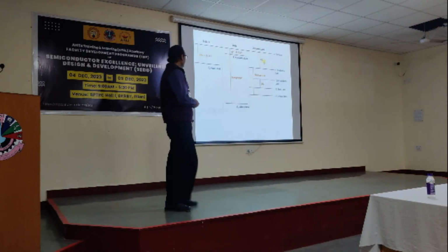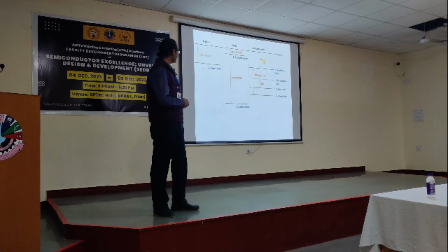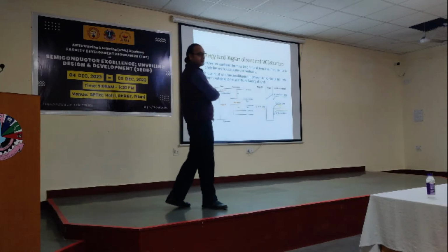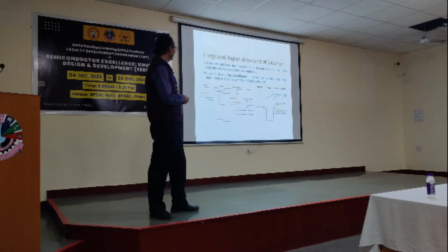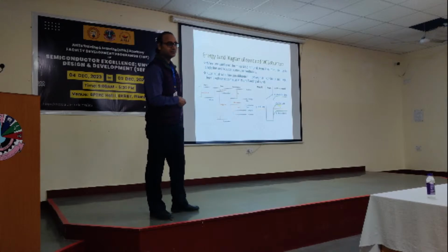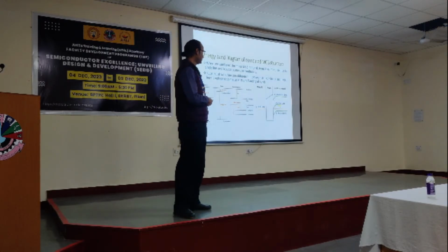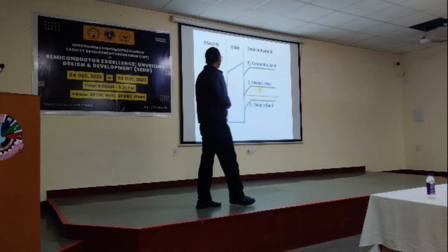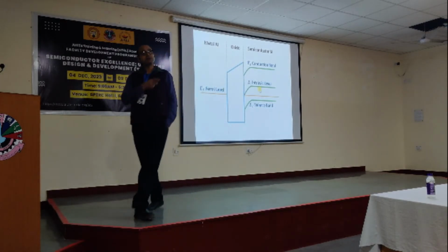Okay, so this is discussed. Now, as I said, under that condition, what will happen? Everything we have discussed here, the only thing remaining was the bending. So as I said, electrons will shift towards the semiconductor here. That means holes will get reduced at the surface, so the valence band will move down, right? Why? Electrons have neutralized certain holes there.